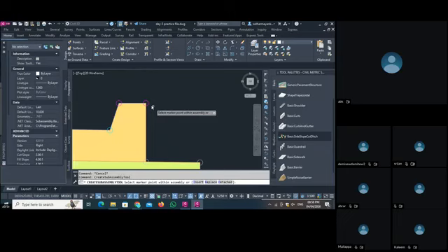So for that, I want to move this sub assembly here. As I select here, our daylight is moved from here to here. Okay. So now your full assembly is created. But see, here on the corridor section, you can't see anything here. So we select our corridor, and here you can see the rebuild corridor. As you rebuild the corridor, click OK button.